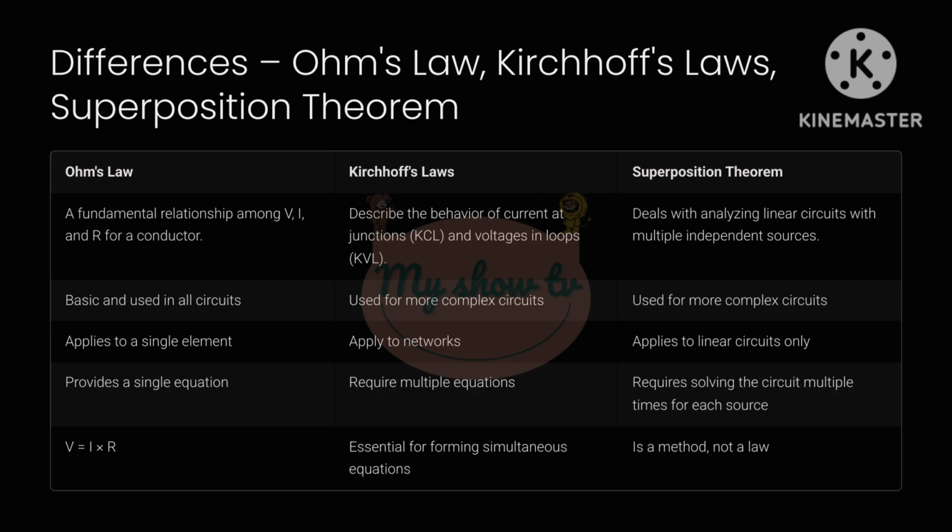Now, let's compare the three concepts to understand how they are different in purpose and application. 1. Ohm's law is a basic law that defines the relationship between voltage, current, and resistance in a single element. 2. Kirchhoff's laws are used for analyzing entire circuits, KCL for junctions and KVL for loops. 3. Superposition theorem is a method used to analyze circuits with more than one source, by considering one source at a time.